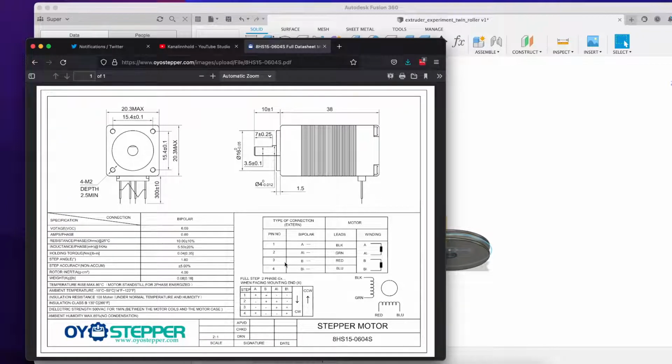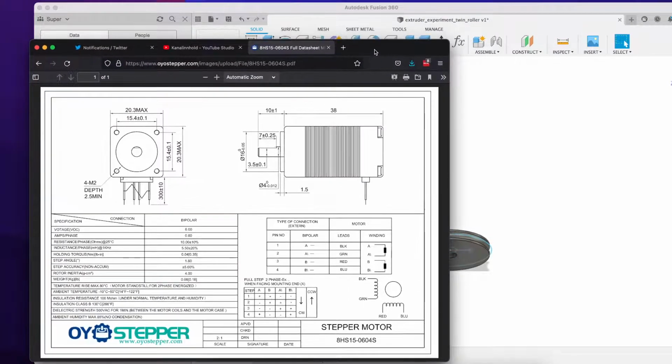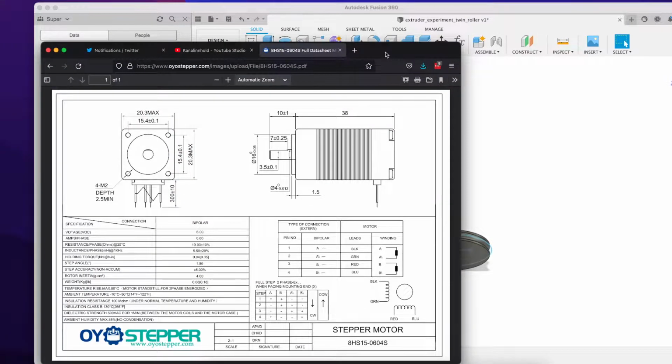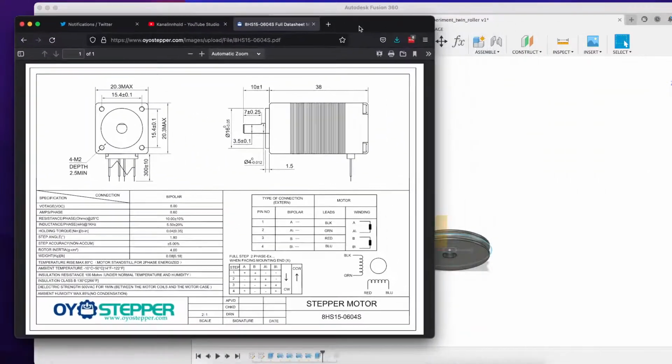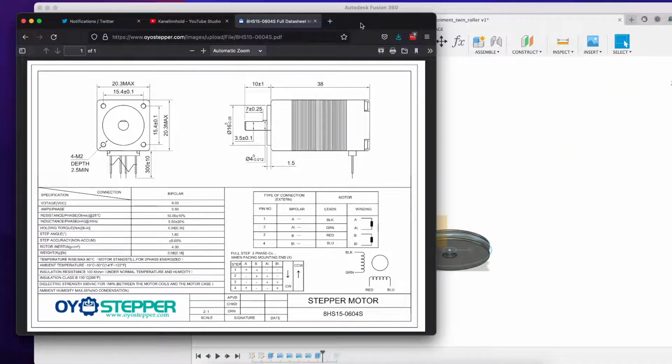Because obviously stepper motors usually just run on the power that they get. But you can check the load by checking the load angle from a proper motor controller, like the TMC5160 from Trinamic. So let's get these measurements.